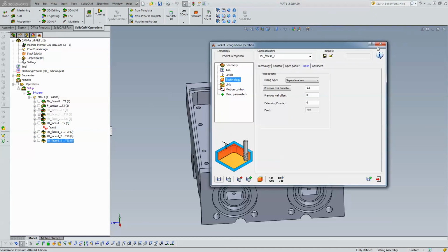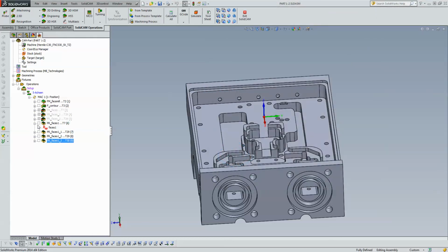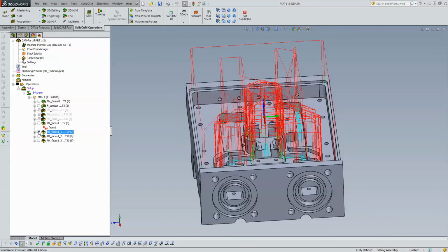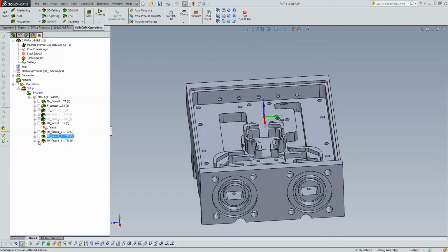using our roughing operation inside over there, then going down further to the next area, roughing those out wherever that previous one could not work, then doing a finish on the walls, and then finishing off in the areas where the previous operation could not work. That's what we saw in this part.